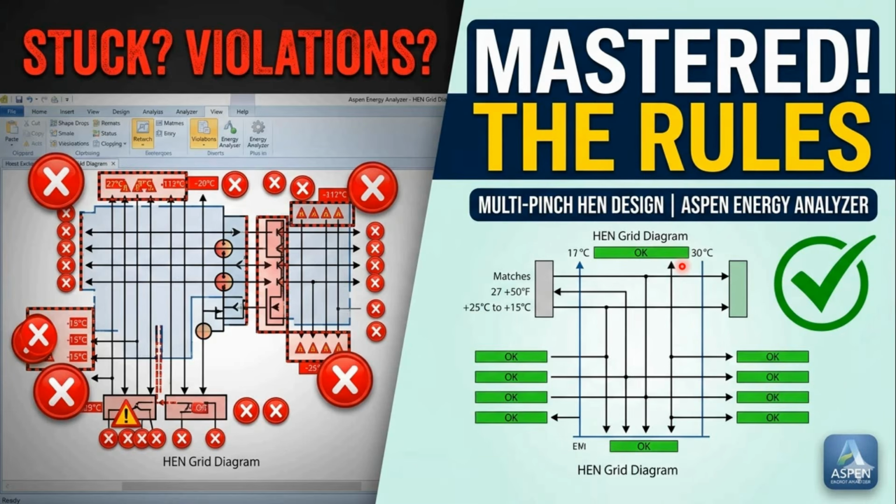You have set your delta T minimum, you have identified your pinch point, and you have started matching streams. But suddenly, the math breaks. You have a temperature violation you cannot fix, or your utility targets are way off. The problem? You are not dealing with a single pinch problem, you are trapped in a multi pinch network.